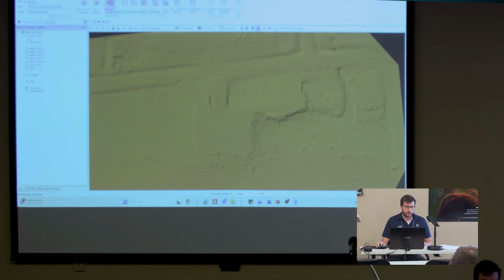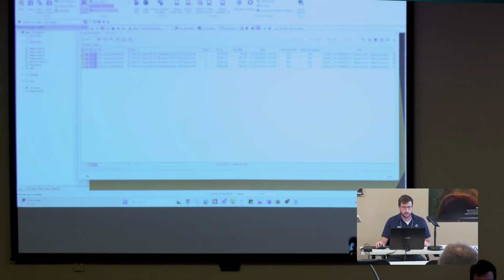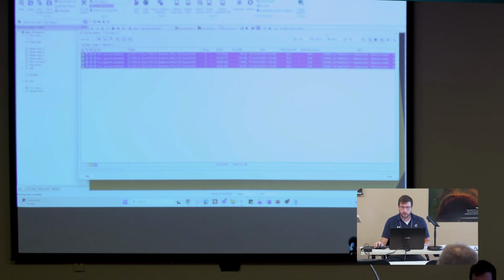Okay, so let's run this by active layer. This should go pretty quick. And then after we run this, we're just going to look in at LAS file analyst to see how many points were thinned, how many points are put into the model key points flag. So click OK. Go to project in the top left. Click on LAS file analyst here. I'm going to do a left click on the row, do a Control A, hit scan.